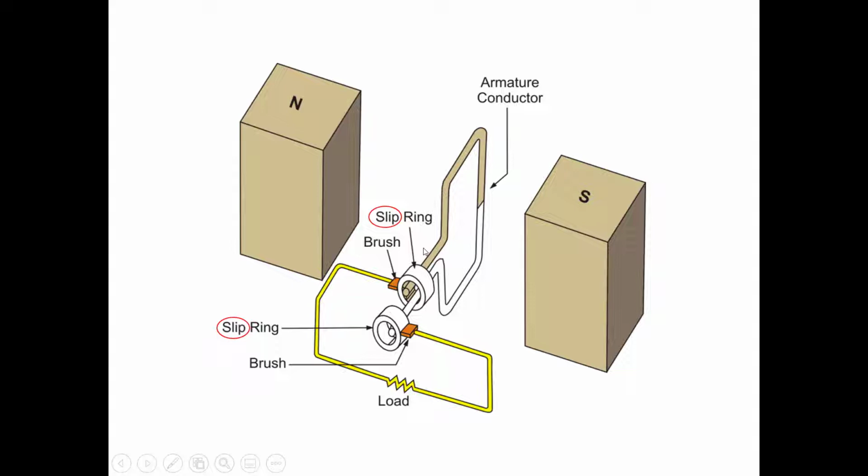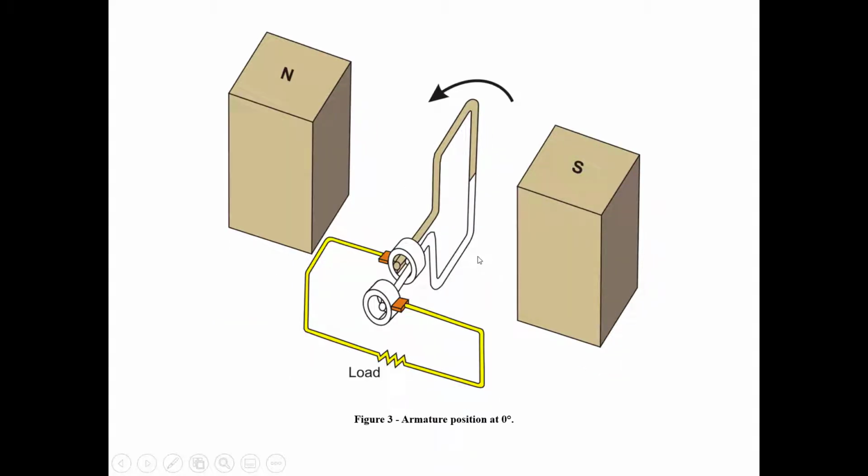The other thing that we want to make a point of here is the difference between slip rings and split rings. When we're talking about AC generation, we use slip rings. It's a connection point with the brushes here and here for our load. Because this is spinning around, potentially at 60 hertz, we can't have a connection that's solid to that. Otherwise, obviously, these wires would just get all wrapped around each other. So that's why we have slip rings and brushes to minimize the arcing, where it just sits and makes contact. The whole time it's spinning around, it makes contact and then puts a voltage to our load. So in AC, we're going to use slip rings, because this thing is going to be spinning around, and we want to see that positive peak and that negative peak in our sine wave.